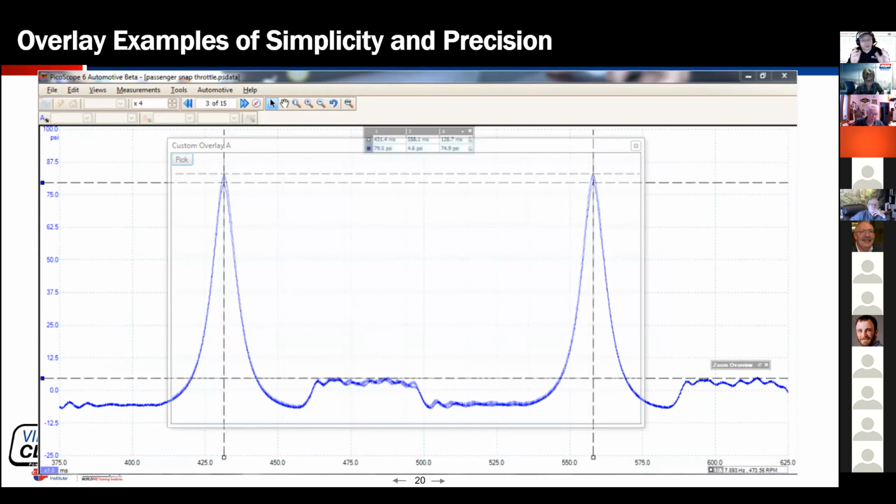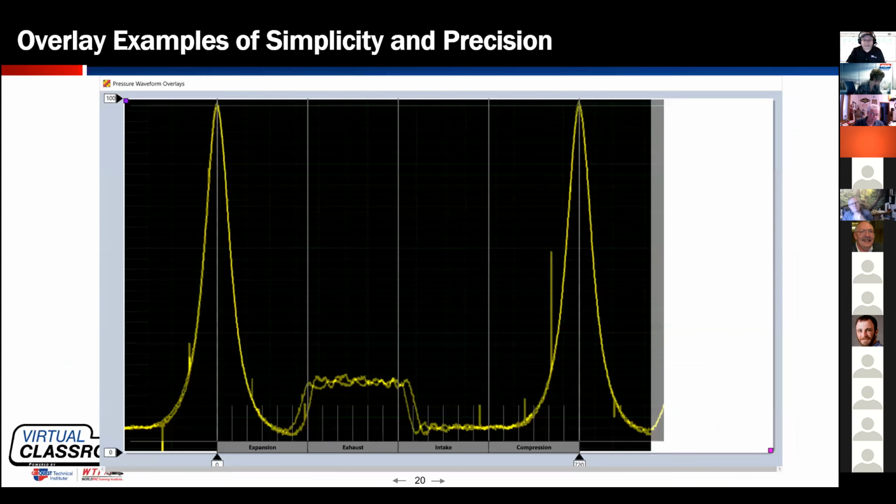There's quite a few rules to doing this. But what I wanted to get across to you is you'll notice as I decompress and I come to the point of the exhaust valve opening and it ramps up, and my exhaust plateau and the drop into my intake event and the depth of my intake plateau and the closing of my intake valve, my one bank looks identical to the other bank, indicating at least the two banks breathe the same. So when I say they need to be close, I'm telling you, they need to be that kind of close, not this kind of close.